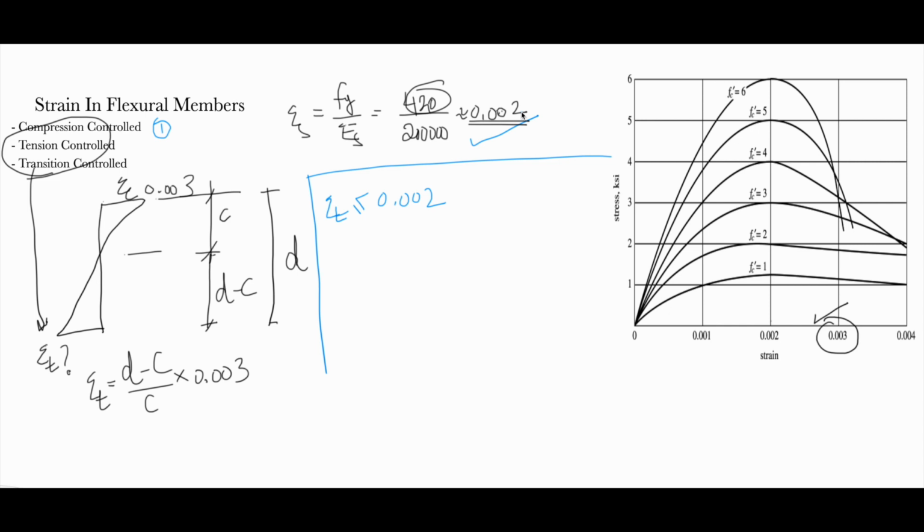So what does it mean if I design my beam based on this? That means the beam can fail suddenly without any warning. By warning, I mean the deflection. When you see a beam or a slab that deflects, it is giving you a warning that it is under stress. That means there is something wrong.